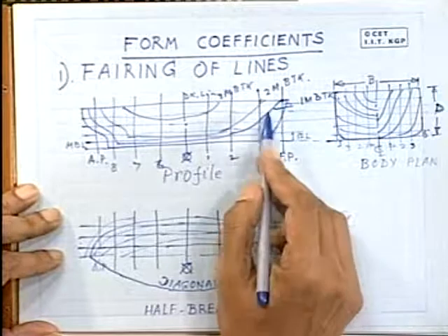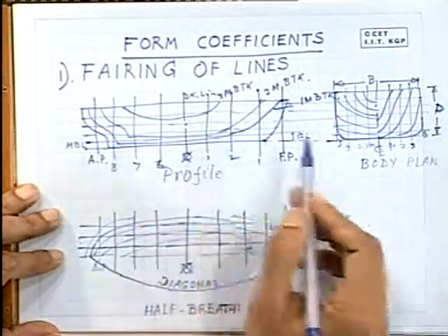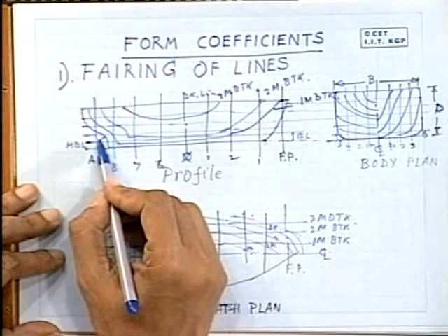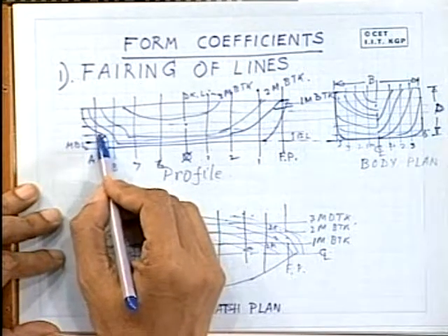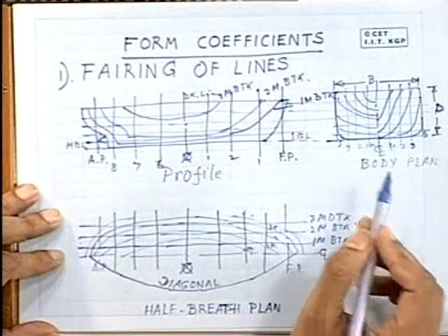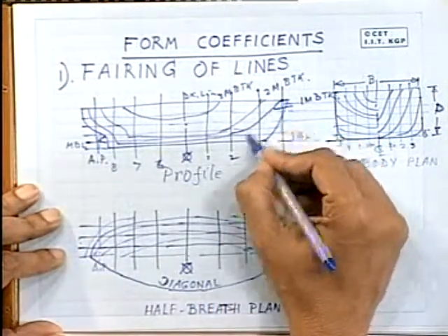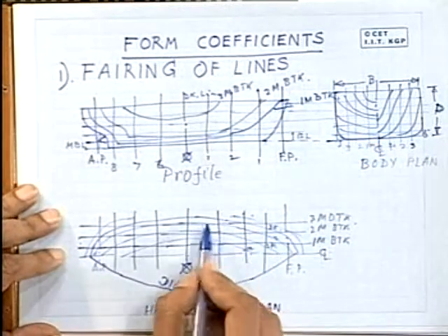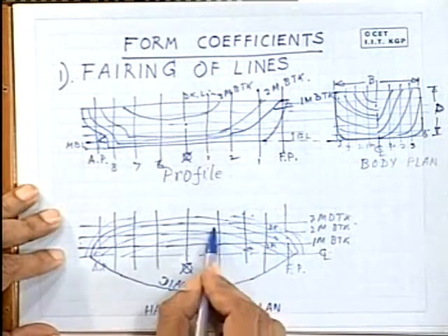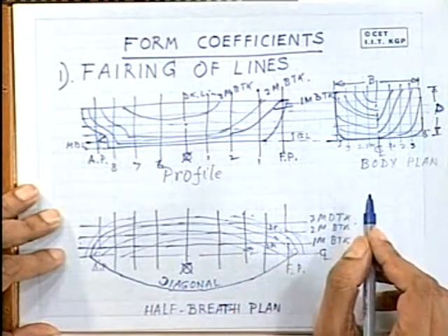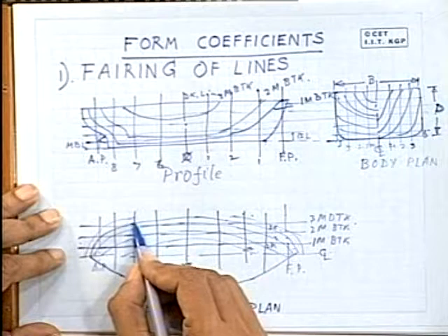Now, from the naval architecture point of view, this flow of water to the propeller is of very large importance. So this flow is governed by the slope of these buttocks or slope of the water lines. This distinct slope of these lines actually varies from ship to ship.